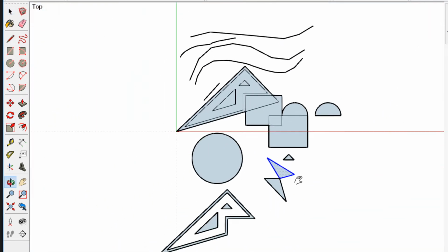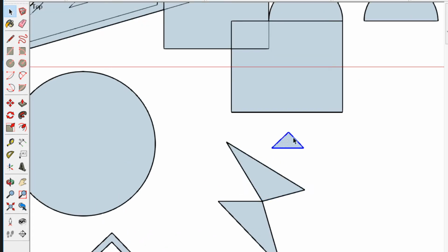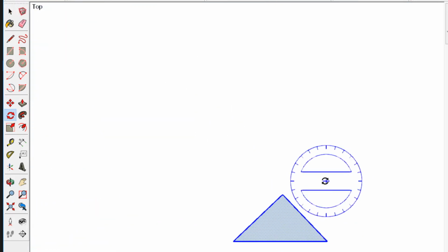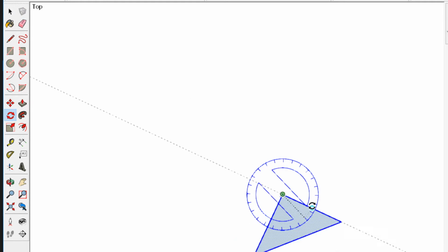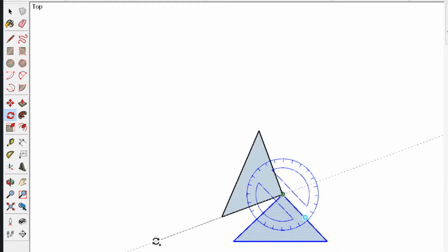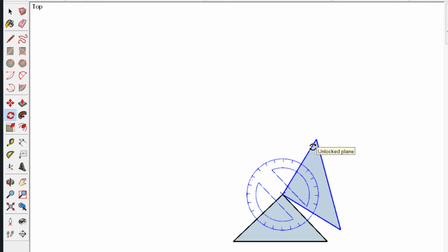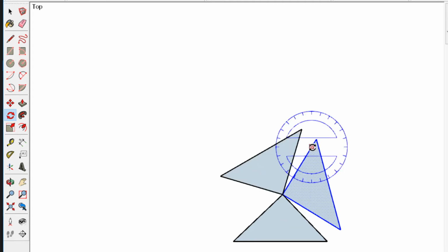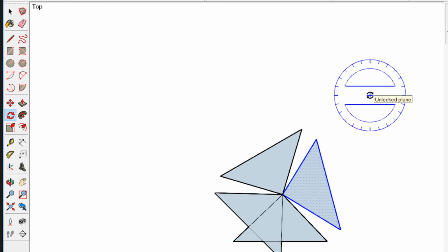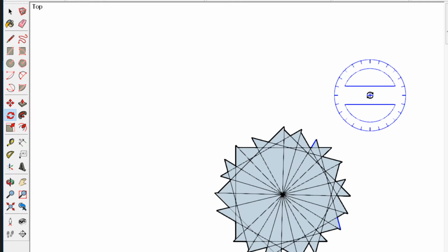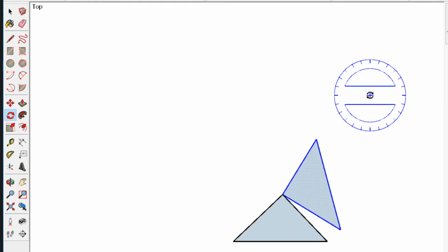Okay. How do you multiply copies? Let's say this, I press Control with the rotate tool. Let's say I want this distance. I click on it, and without putting any other command, I click like 2x, so 2 times. It creates 2 copies. 3x creates 3, but it overlaps. 4x, 4, 5x, 5, 15x, 15, 1x, just 1.